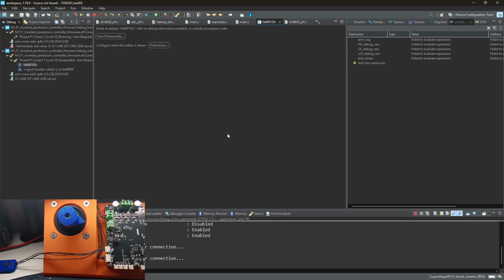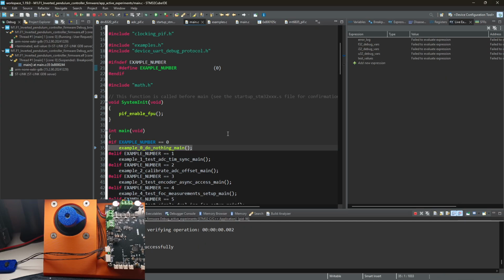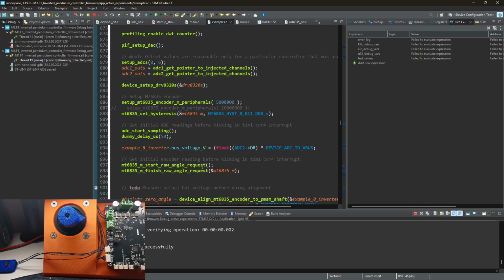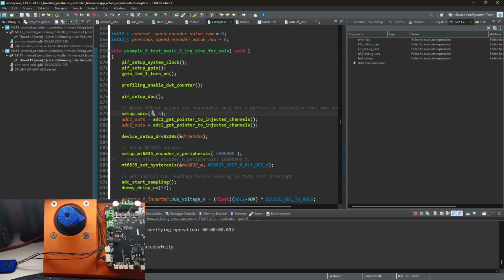No, this is not how FOC is supposed to be implemented. Trust me. I was hitting current limit quite a few times, so let me raise it up a bit. My power supply was not happy about it at all. But okay, let's set our correct calibration values. 10 turns.